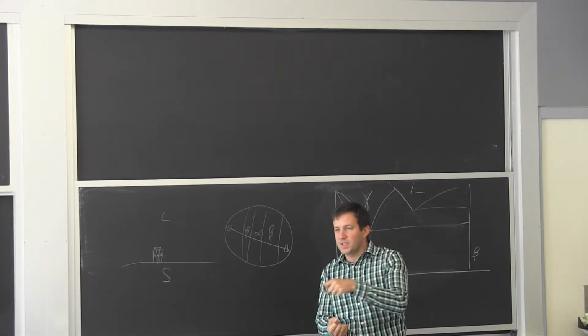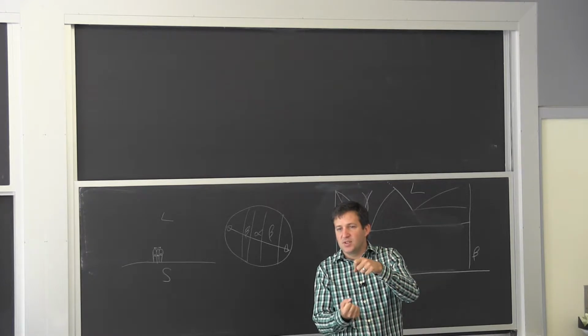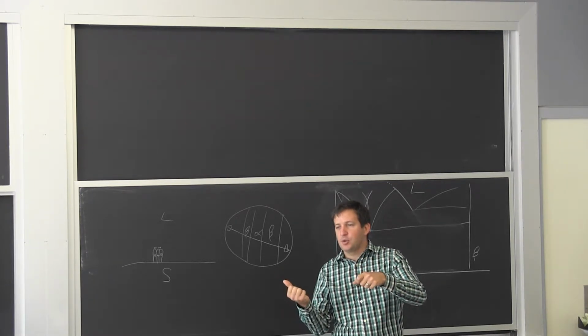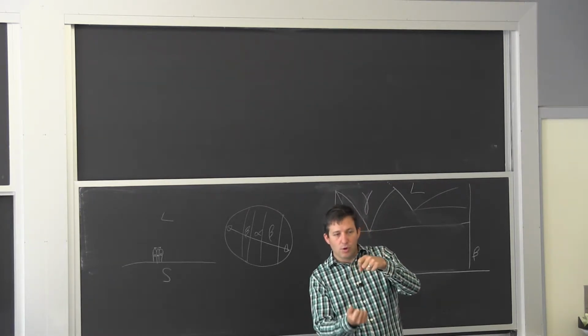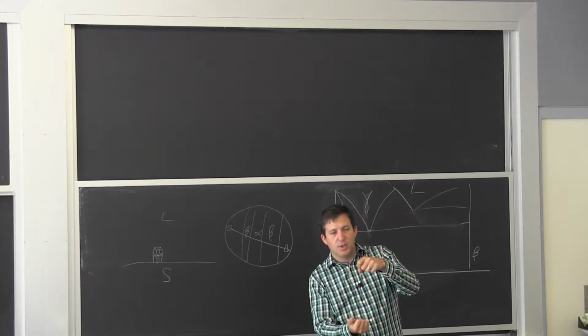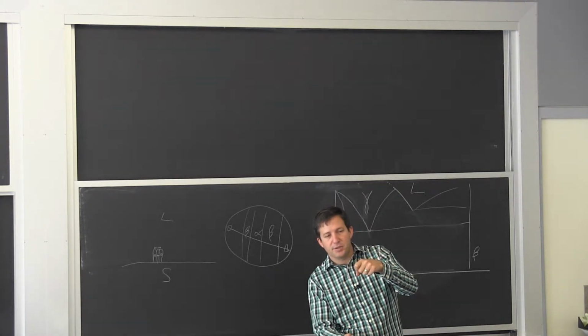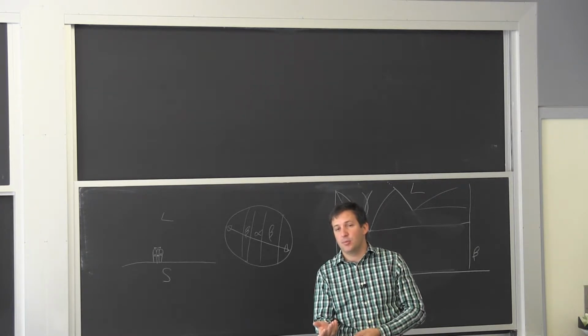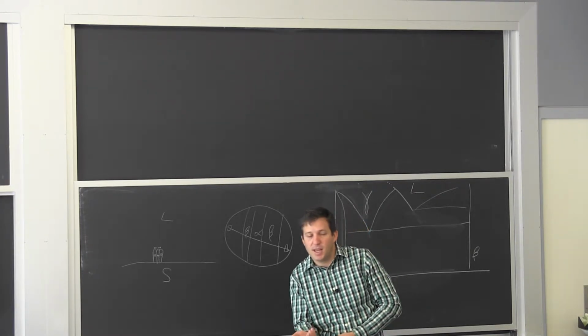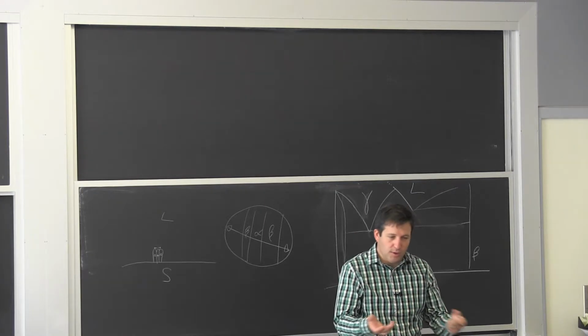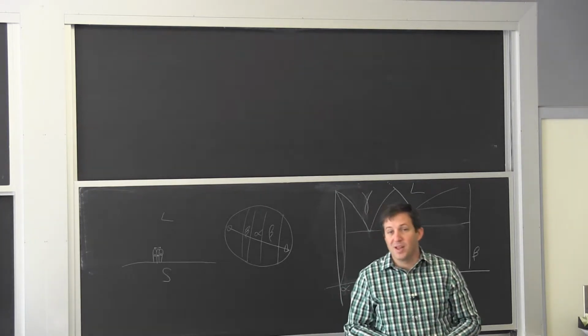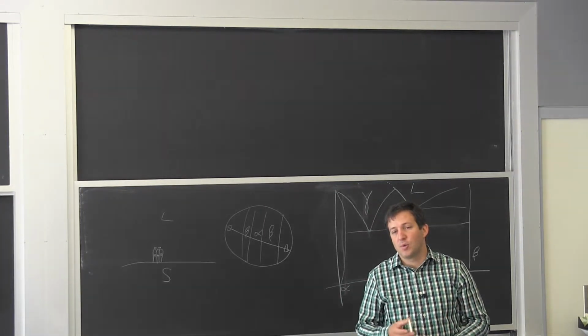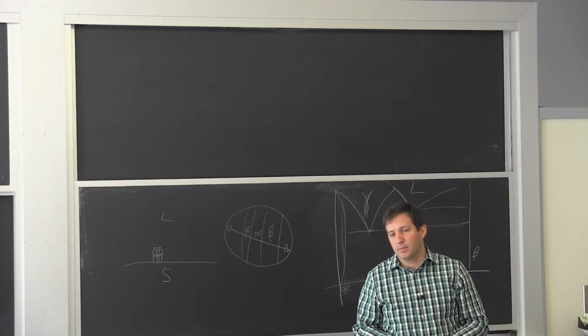So when you're looking at 0.6 here, that's the same condition. It means the steel at the temperature where we form it, if I just put a dead weight on it, is going to continue to stretch and stretch and stretch. A little bit like a polymer does at ambient temperature. The reason the polymer does it at ambient is that its temperature of melting is much lower. So you're above that 0.5 temperature of melting.